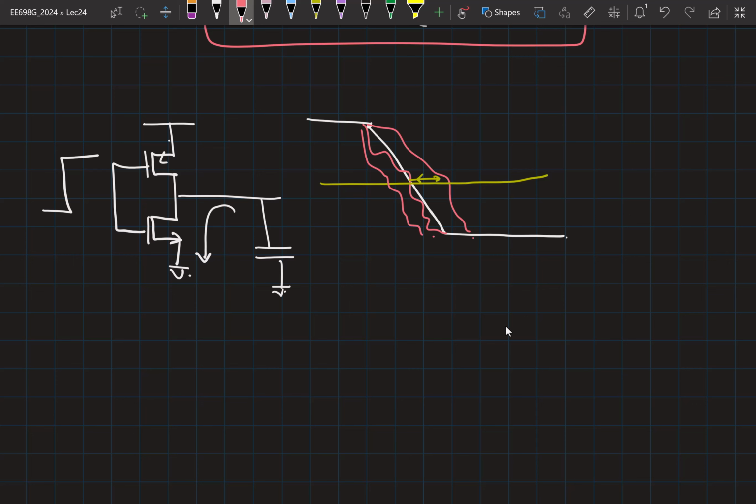Do you think the PMOS has any effect, noise of the PMOS? Let's assume leakage current. Leakage current part I understand, but if there is no leakage current, does it have any effect? It has thermal noise and flicker noise, but it is cut off, right? It is completely off. Then does it have an effect? You are assuming subthreshold conduction, and because of that. Again, I agree.